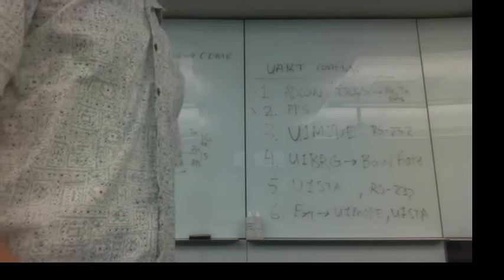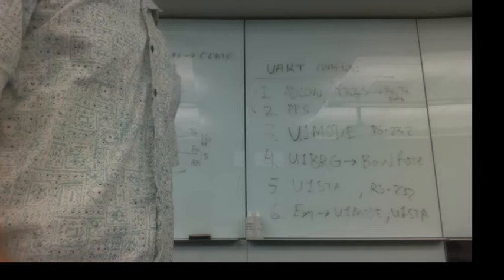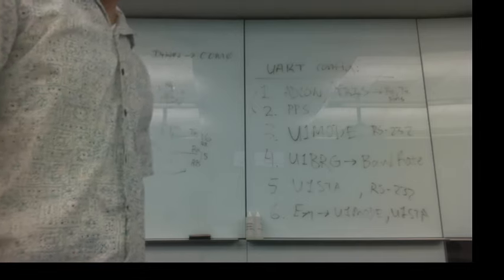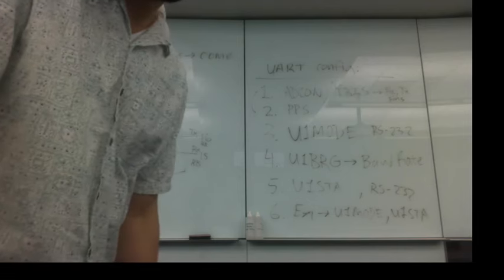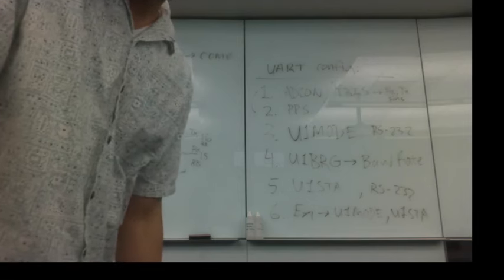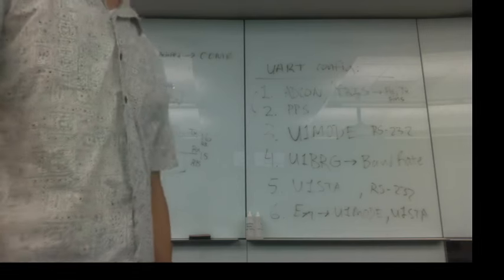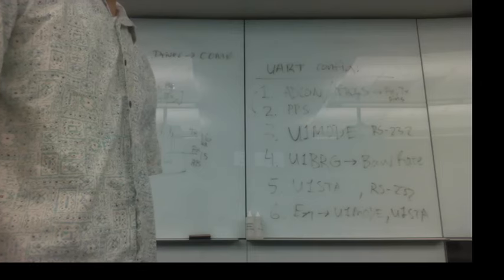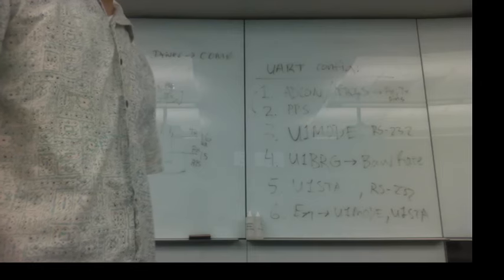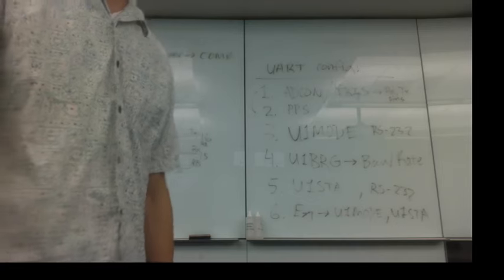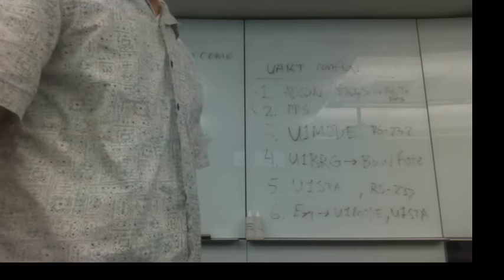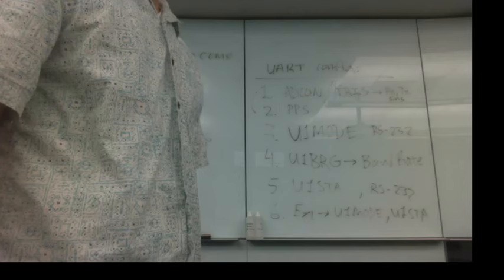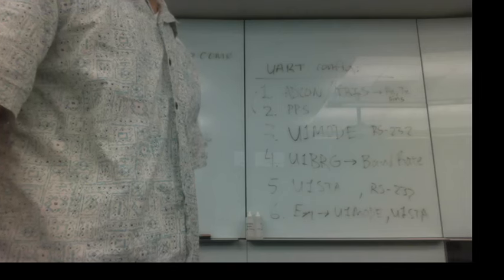One thing that we will use is the UART enable bits, they call it, which is kind of confusing. They have one thing called UART enable bit, and another thing called UART enable bits. Those are bits 8 and 9, and what those do is they configure the different flow control modes. So 00 is what we'll use.